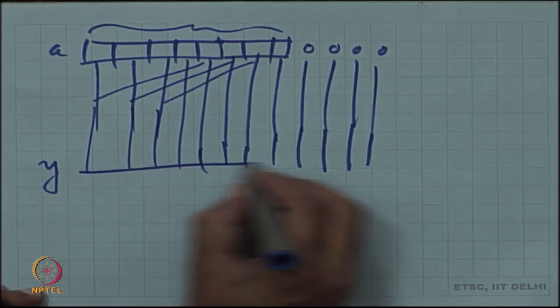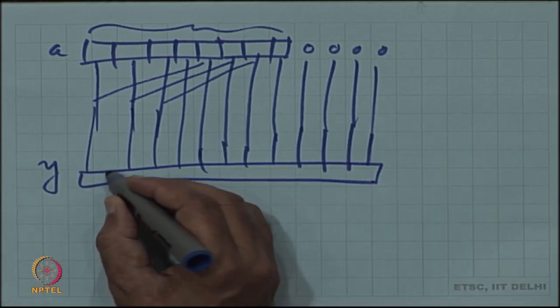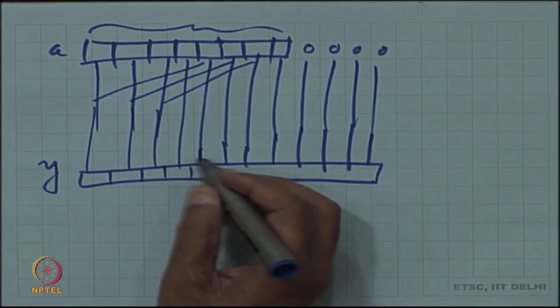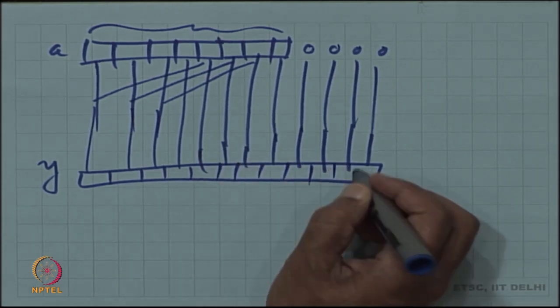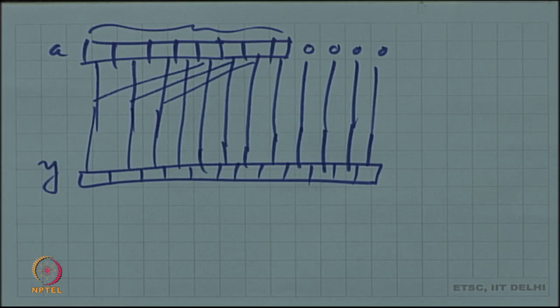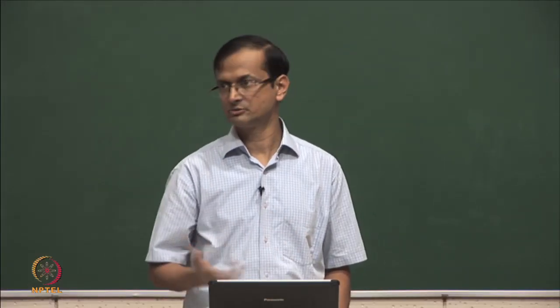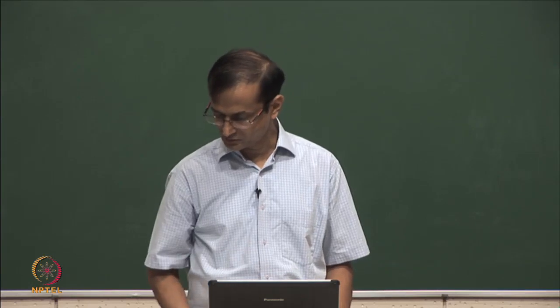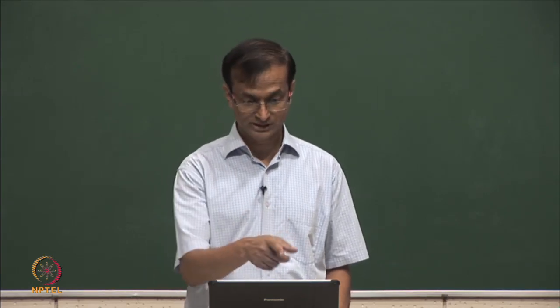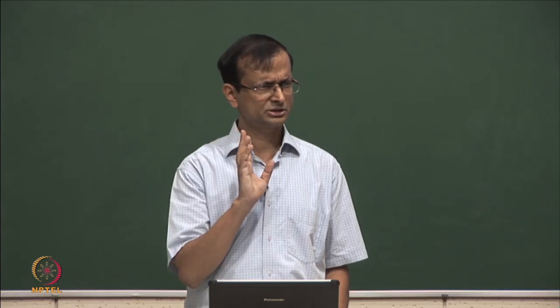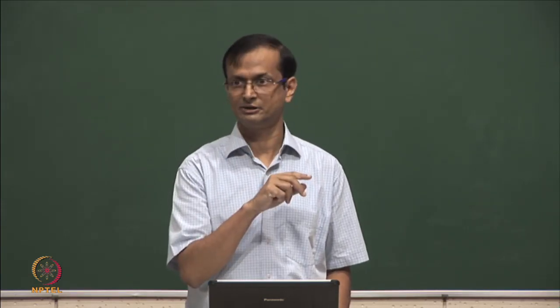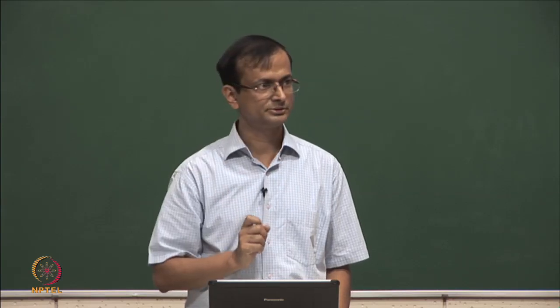Y needs to be stored here. If this Y is to go into a register, then a 12 bit register is needed. So, where should I put the shift register? You remember, if Y was 8 bits, then what should we do? An algorithm is clearly there, shifting by 4 bits or 3 bits or whatever it is. I am just trying to find out what the hardware is. When I say cheaper, I have to have a hardware structure in mind, so that I can say it is cheaper than a multiplier. So, what hardware are we talking about here?